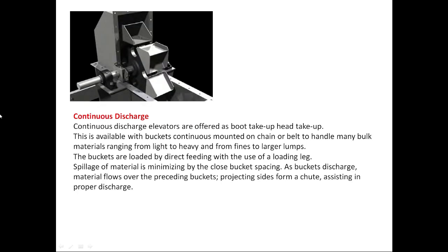Continuous discharge. Continuous discharge elevators are offered as boot take-up and head take-up. This is available with buckets mounted continuously on chain or belt to handle many bulk materials ranging from light to heavy and from fines to large lumps. The buckets are loaded by direct feeding with the use of a loading leg. Spillage of material is minimized by the closed bucket space. As buckets discharge, material flows over the preceding buckets' projecting sides of the chute, assisting in proper discharge.